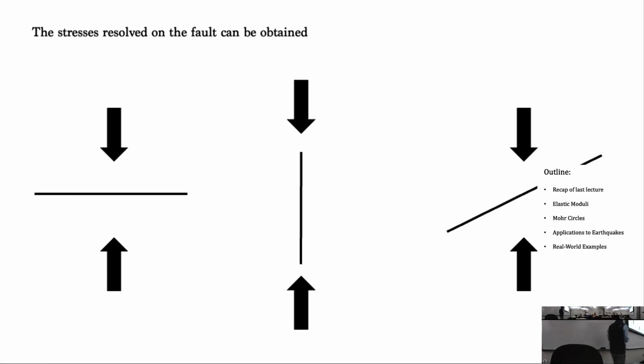So this point is going to plot, there's 0 normal stress, right? The stress acting in this direction is 0, so the normal stress is here. And then for shear stress, I would argue there's 0 shear stress, because you have to have some kind of traction. It's what we talked about before with the tractions. If there's no traction, there's no stress. If you were to take the traction of that force on that plane, because the force and the plane are parallel, there's no actual traction. So this point actually plots, and I want a new marker. Yes, exactly. That's exactly right. So this point plots right here, and let's call it beta.